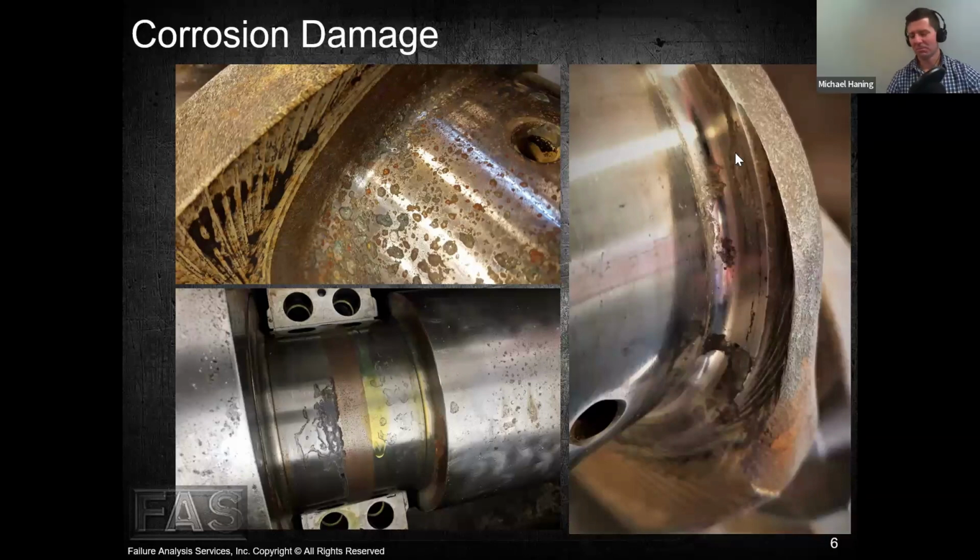Ouch. This crankshaft here on this engine, when we see this damage right in the fillet radius, oftentimes that occurs when a unit is stored outside and not protected properly from outside elements, meaning that if it doesn't have any of the exhaust after treatment, such as a catalytic converter or catalyst or a muffler, then sometimes we'll see foil tape used, or a type of tape, on that flat top exhaust flange.